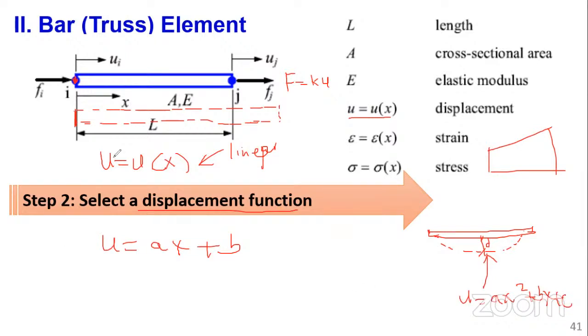So we start with a bar element. We are saying it behaves in a linear manner, so this displacement function u(x) we can express as an equation of a straight line. And I hope now you understand where we are getting these assumptions from: from the assumptions that we define. We know it can either elongate or compress, with no other form of deformation and no other degree of freedom. And then we are saying the material obeys Hooke's law, a linear one. So basically, our function u(x) can be expressed as a linear function, and you can see we are expressing it as a polynomial. Okay.